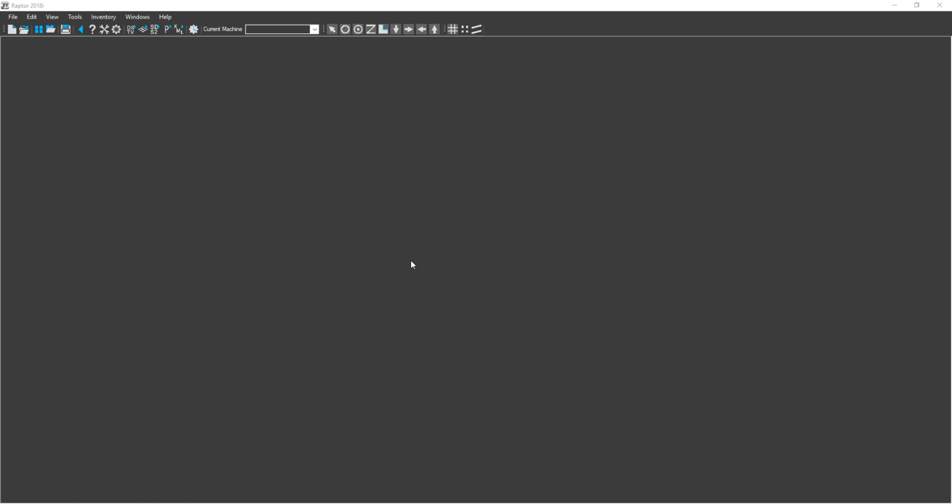The purpose of this video is to describe the Tekla import process in Raptor. To begin, you must have Tekla open on the computer you are using, and Tekla must have been open before Raptor. You don't need to have the Tekla model open before you open Raptor, but you must have Tekla open first. Once Tekla and Raptor are both open and you have the model open, you can begin the import process.